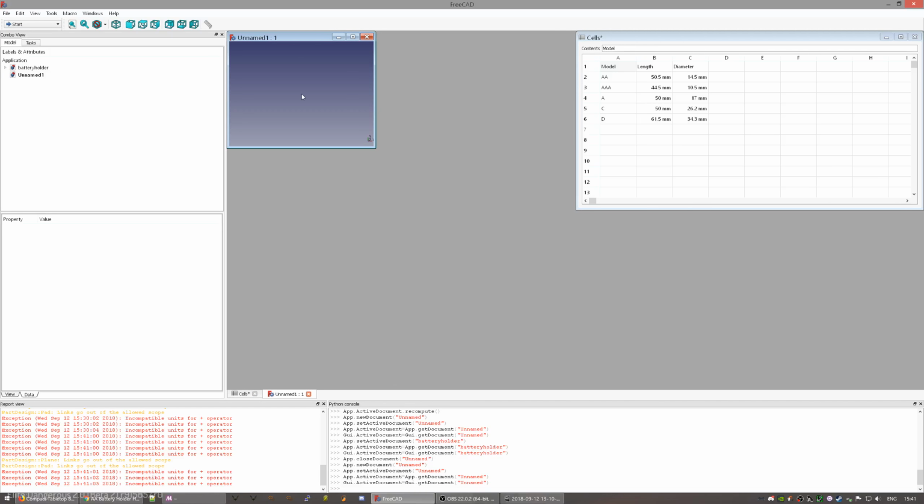FreeCAD does not come with an easy way to move the labels between cells, and you have to select an individual cell and apply the alias in the cell properties dialog. Now, granted, when you are in the spreadsheet workbench, there is a shortcut to the particular tab, but it's still opening a modal dialog box for every single cell, and it's a pain.